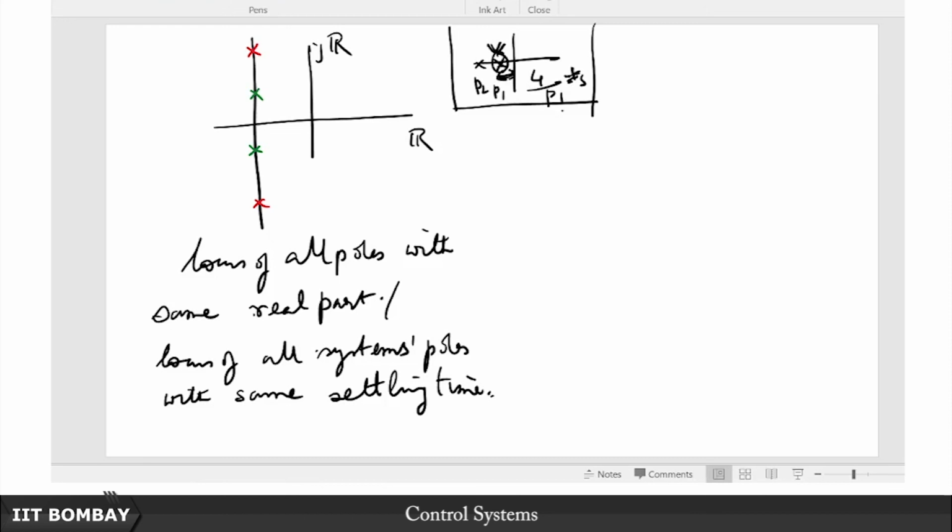So I just wanted to put that discussion to rest, because you might wonder that there also should be a settling time expression or a value for overdamped systems, and you might be confused as to what that should be, because there are now 2 distinct poles. For complex poles both these poles will have the same real part, so we do not really care, yeah, they will both have the same real part and opposite imaginary parts, opposite in sign. But for a real pair of poles, which is an overdamped system, right, you have 2 distinct real poles.